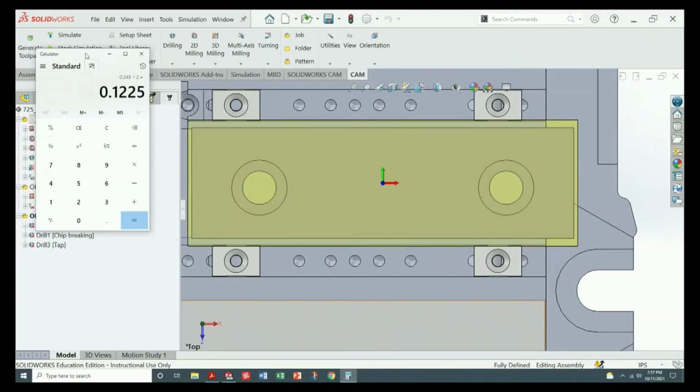Facing is done, with the face toolpath and a depth repeat. What tool do I want to rough profile my part with? The roughing tool, the same one I faced with. All right, tool 1. So, do I need to put a tool change in here if I'm going to stay with the same tool? No, I don't need to.